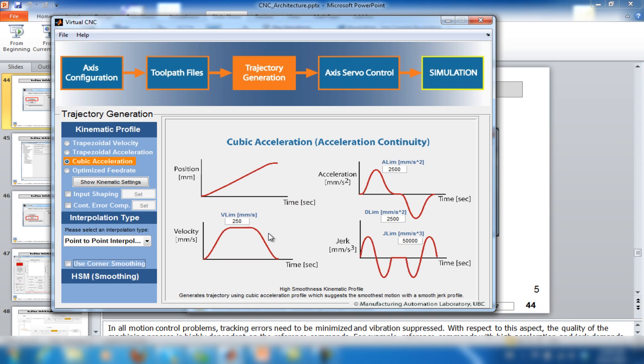What they do, like we do, they put a small micro spline in the corner. So the machine never stops, and the velocity transitions from one direction to another become smooth. We don't know how they are doing it. They never tell. From that point of view, it is very difficult to estimate the cycle time of a commercial machine, although everyone is asking us to do it.